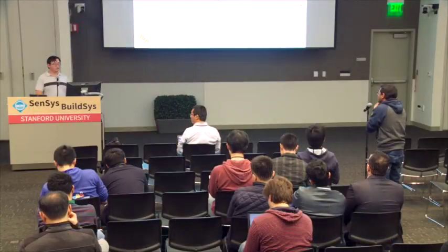Well, the reason we use this is because Bluetooth, of course, frequency hops. For each of the frequency slots, you have to basically schedule a certain amount of packets. In one instance, you also have almost non-ordered arrival times. That's why you have to schedule the packets into a specific time and frequency, and that's why we use multiple buffers. Could you suggest any other better ways to do it? Yeah, there's probably other better ways to do it.